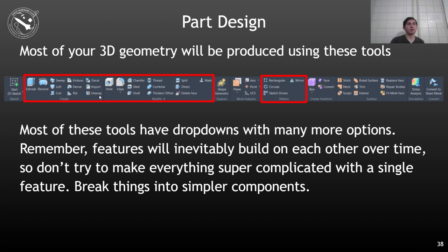There's a handful of other things here. There's also the hole tool. With the hole tool, you can basically pick a certain point on a sketch and you can either have some sort of a clearance hole that lets a screw just go all the way through it, or a tapped or threaded hole that the screw actually goes into and engages and turns into. You can pick a variety of different standard holes for standard screw dimensions.